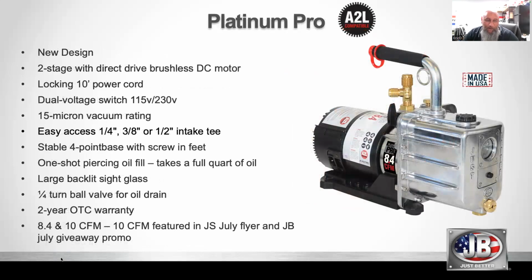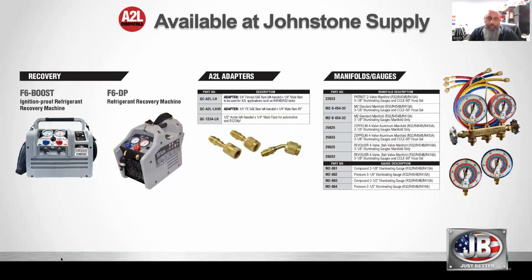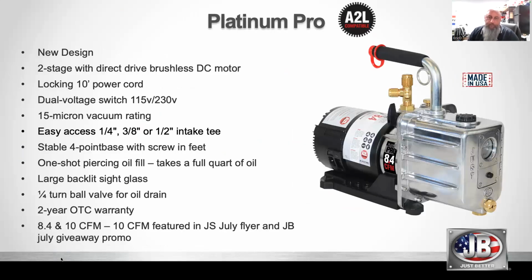We have the Platinum Pro, which is our new range, designed specifically for A2L. It was designed from scratch with a brushless DC motor. It's got a brand new oil management system and a big backlit sight glass. The oil fill system's great.